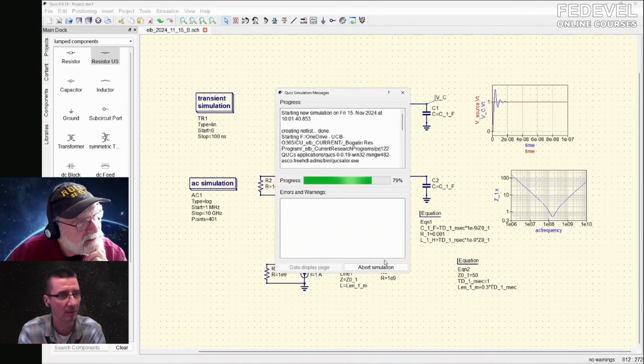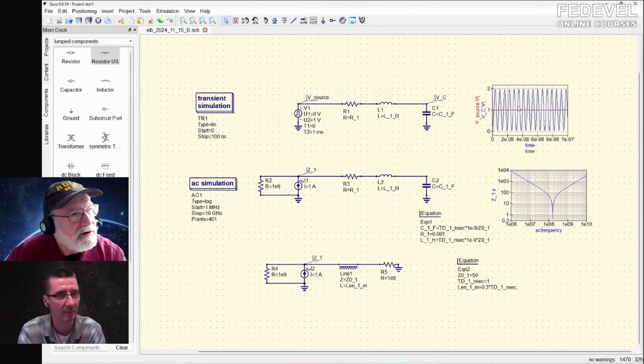And it's taking a little time. There it is. Oh, okay, I made the Q really high, so it's got a lot of ringing. It's ringing forever. Here is that impedance profile. It's going down here, I didn't happen to hit the lowest impedance, so it only went down to 0.3 ohms here. And now let's add this impedance over here. This is the impedance of the circuit 1, the RLC. Let's add the impedance of this guy.